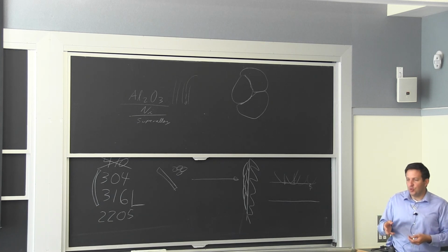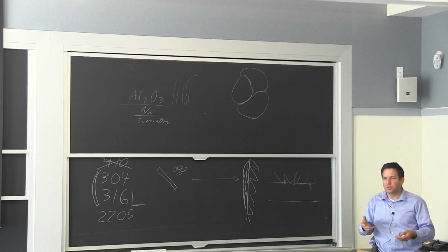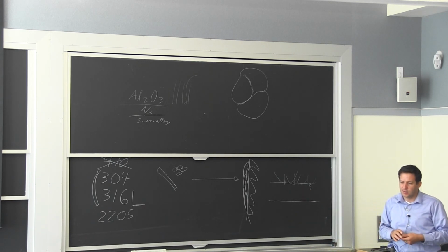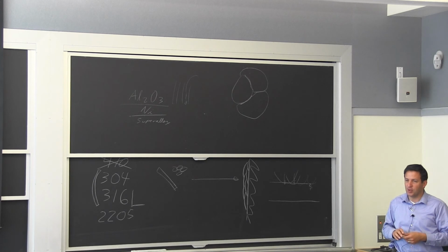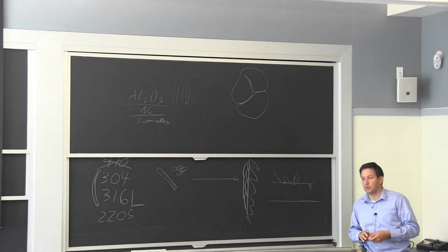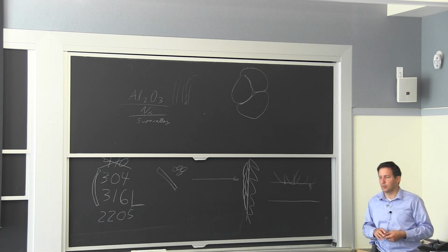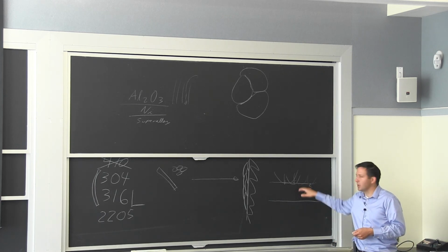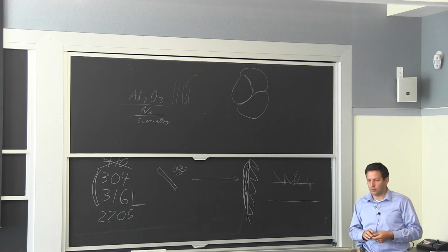I've seen it confused with what I call shot peening, because they will use some form of a peening term. Sometimes the chain that I brought to you, the aluminum chain, was apparently shot peened. I would say it's just mass finished to clean it up, essentially. So it's very different from my standpoint. The shot peening I'm talking about really creates that compression layer on the surface.